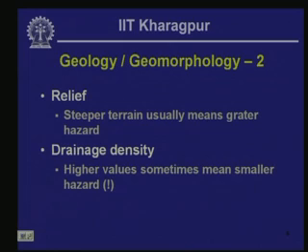If you have a greater drainage density, that means a greater amount of runoff is exiting that area as surface runoff, and very little is getting into the material underlying the slopes. And because we have seen from the previous discussion that when the slope becomes wet, or when water percolates into the slope, then the water table rises, and the erosional activity increases near the bottom of the slope.